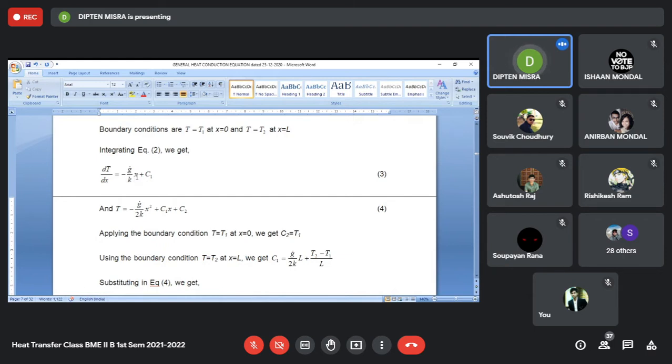It is varying with x, and that indicates that the heat flux also will change with x, because heat flux is simply temperature gradient multiplied by minus k. Because the temperature gradient is changing with x, the heat flux also will change with x. And when the gradient changes with x, that means the nature of variation of T is not a linear one.